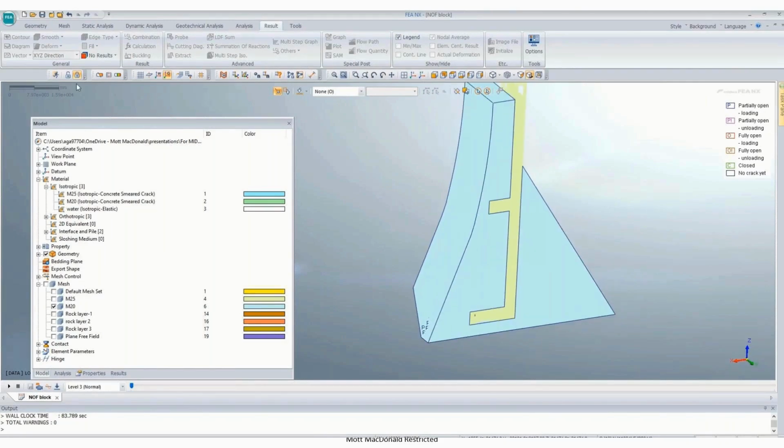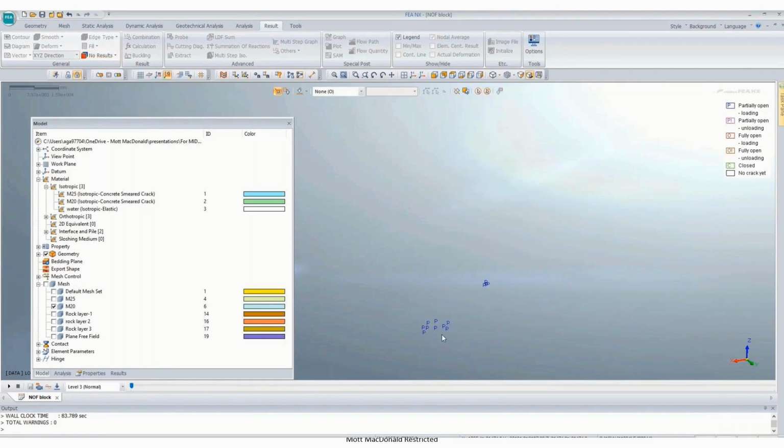I'll change the display mode. No results, so I'll exclude it. So we have some tension here and some tension in the lift well region. That is some minor tension, more than 0.3 MPa, so we definitely have to provide reinforcement, and these are partially open.